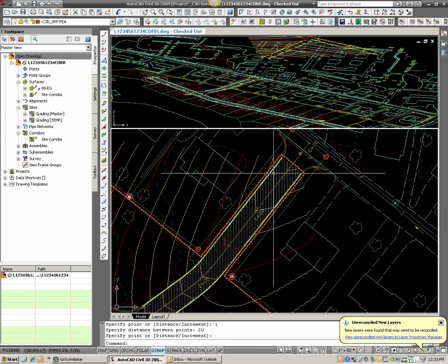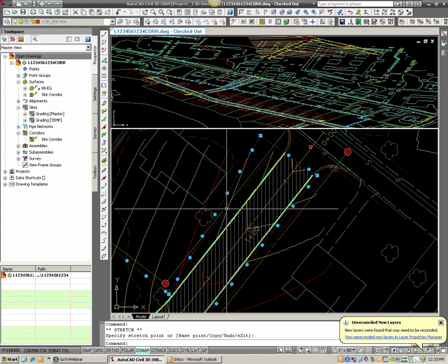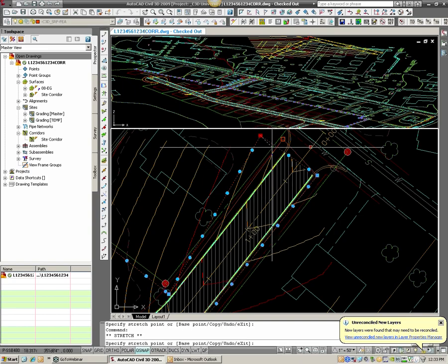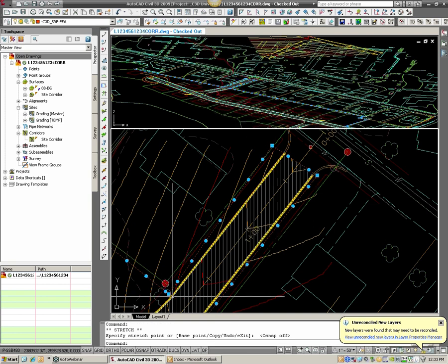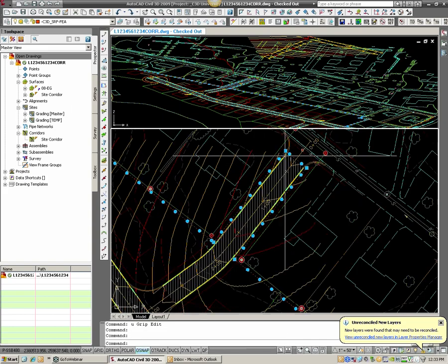What an elevation point is, that's different from a vertex, is if I added a vertex every 20 feet, when I would grab this line and slide it over, it wouldn't act the way it just did. An elevation point only holds elevation. So each point along this feature line can have a different elevation, but if I grab the main vertex, which is this square up here like a normal AutoCAD line, their X and Y coordinates are controlled along this line, so they basically stay in line. So it's a nice little feature that we didn't have in Land Desktop that we do in Civil 3D. And really that's all I want is elevation points along this.